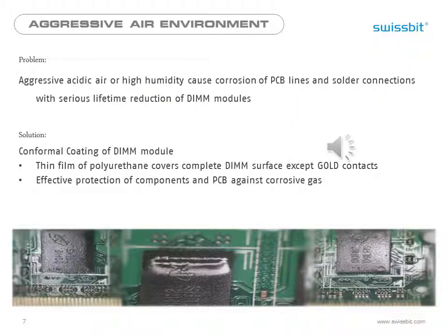Heavy industrial air, loaded with chloride or sulfuric gas or high humidity or dust, can damage any unprotected printed circuit board or solder connection. The thin copper lines corrode and either increase the electrical resistance or finally completely fail. Modules in heavy industry, sandy areas, or offshore operation are likely to see a reduced lifespan if nothing prevents them from being damaged. As a solution to this problem, Swissbit offers to protect the memory module with conformal coating.